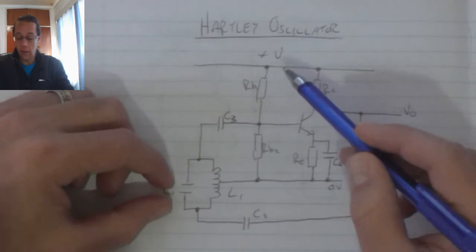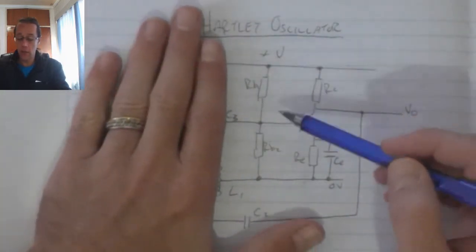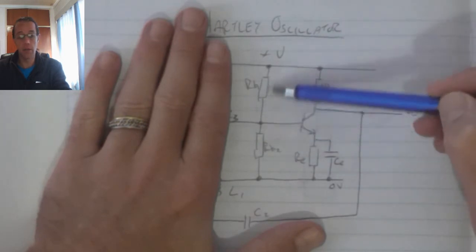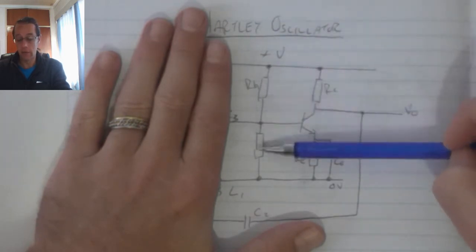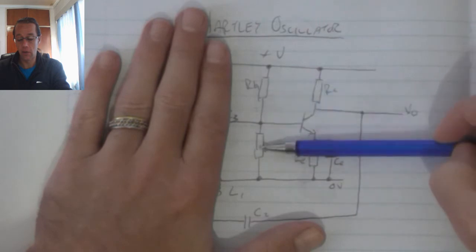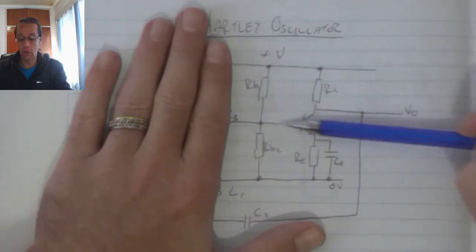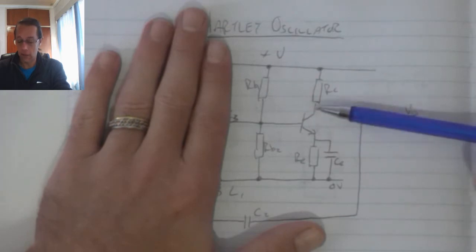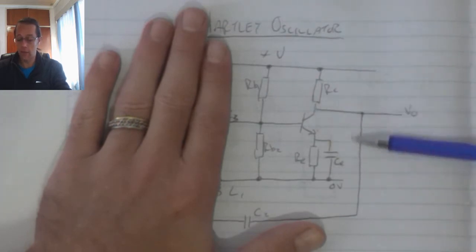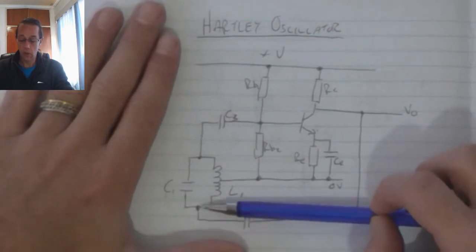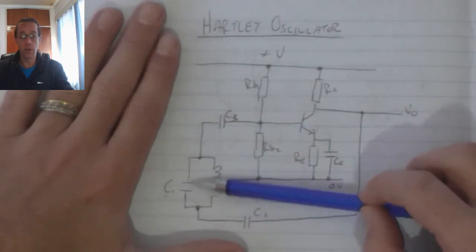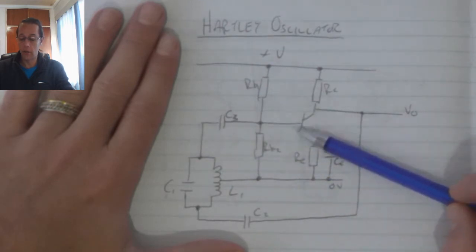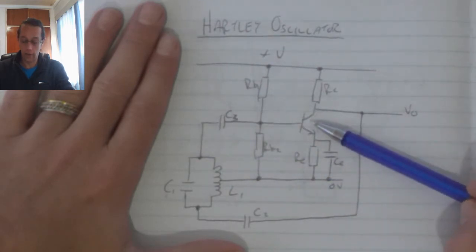When we're looking at the construction, we again see our normal common emitter amplifier with base biasing resistors, or voltage divider biasing. These two resistors, when connected, will place the transistor in the active region. That voltage that it generates is fed back onto the tank circuit, causing positive feedback, which will in turn bias the transistor even further.